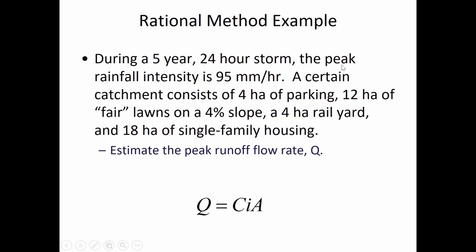Now here, the peak basically means we've already looked at the IDF table and found the rainfall intensity that corresponds to the time of concentration that we feel applies. Okay, so that's the I.